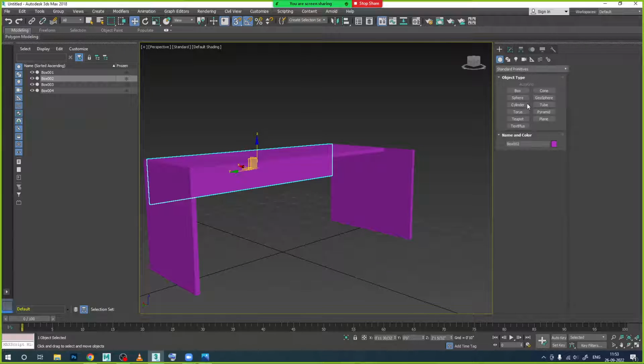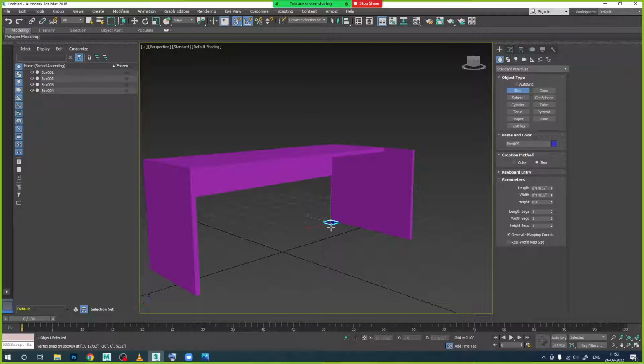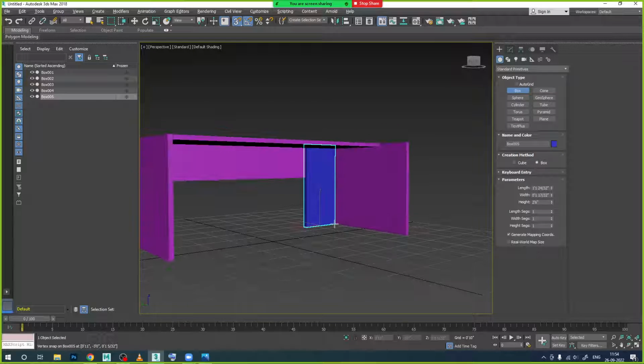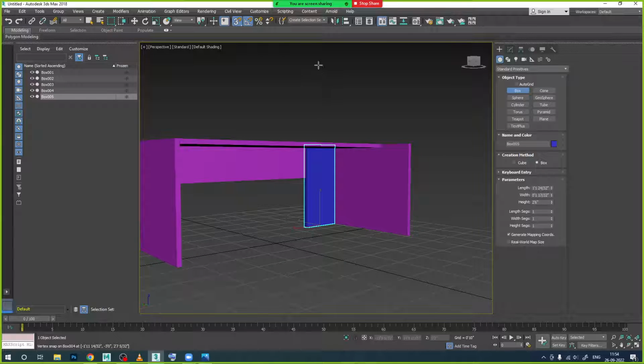Otherwise, if you want proper dimensions, you need to understand what properties we are taking. Just go and snap this one and create length on this one, then width, and then leave and try to attach like this now. See, exactly it has taken the value on this one. Height you can see exactly 2.6 it has taken. While creation only you can have it, but again practice will make it easier to use this snapping option.